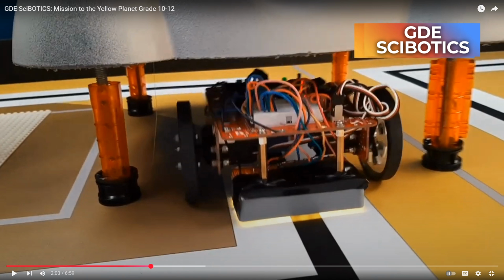So let's just jump out of this programming code and have a quick look at the robot on top of the line. What you'll notice is that the line sensor, which we're looking at here, has a row of LEDs which are simply there to create illumination of the table surface at a certain level. We could use ambient light, but ambient light is going to fluctuate wildly according to where you set up your maze, and maybe you've got a window and the sun comes through late in the afternoon.